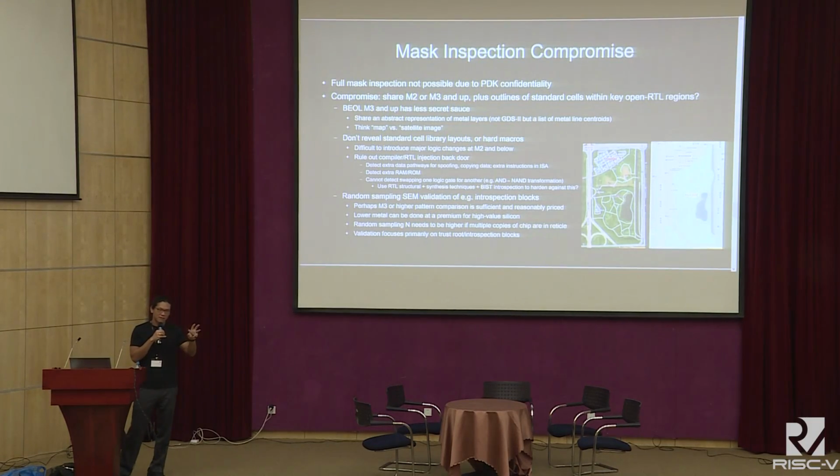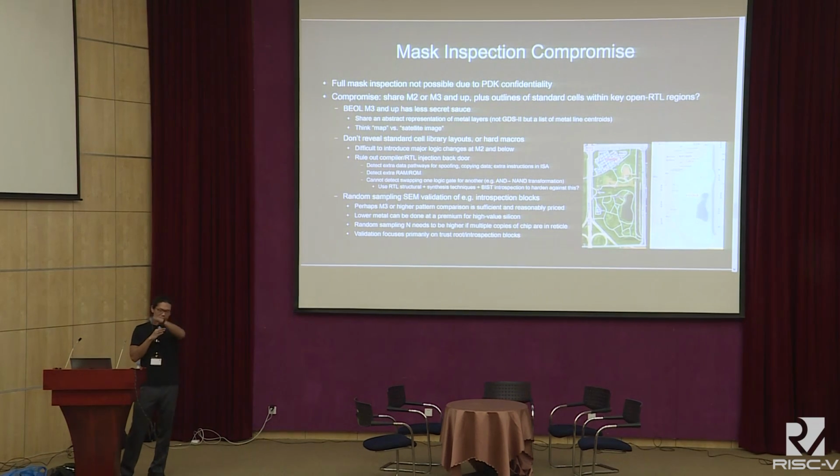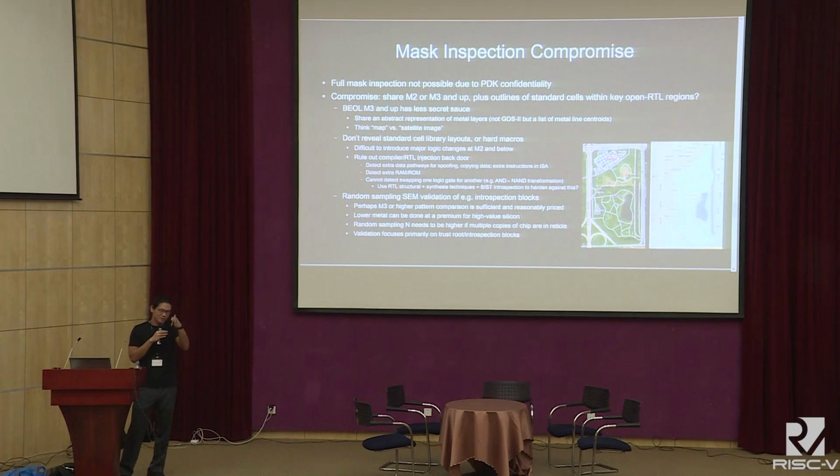So ideally what you would do is, when I was talking about the hardware fences and sort of the BIST tap readout, you would have this empty block in your GDS2 with a bunch of metal pins, and then you would have this little area here, slightly isolated, with the introspection block, and maybe a couple little alignment features. And then this would assist the guys who are doing the readouts, who say, yep, we're just going to look here and confirm that the thing we're using to check these blocks is not modified. And if we can confirm that's good, we can trust everything to the right of this block over here. And so you would design this for inspectability, and then they can go ahead and do some sort of random sampling to make sure that the root of trust is there. And that would be a way to strike a compromise with that community.